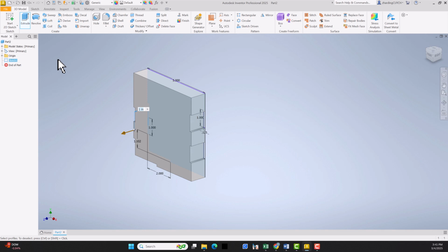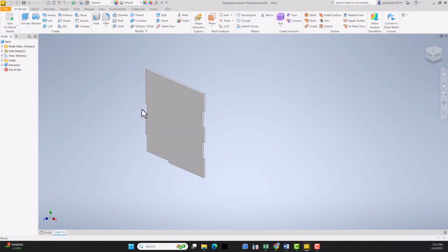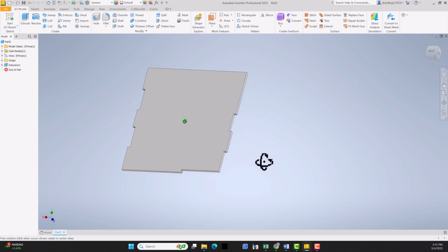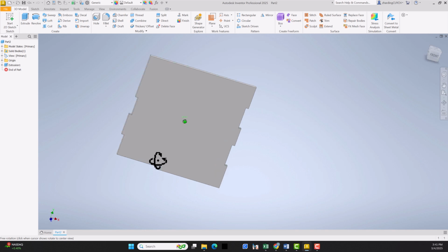But don't overthink it. You want to make sure your widths are correct and your spacing is correct panel to panel. Make sure your thickness of your material is to your actual material, and then create your panel, and then you can move on to assembly, which is in another video once you have all your panels made. Again, this one's not correct. It's just an example to show you how to quickly build without losing your mind.